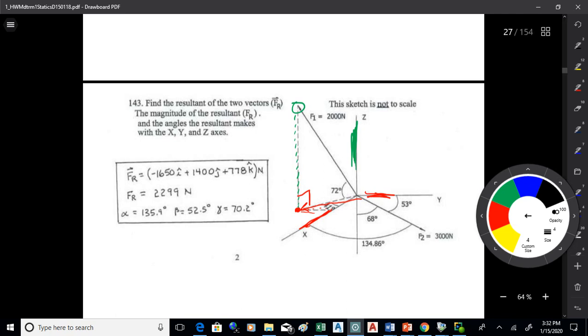So what's happening here is you're given dimension lines that are parallel to the given axes. I give you that dashed line in green right here. That's parallel to the z-axis. That means this line goes straight down in the z direction. Where it lands is on this point over here that I didn't give a name, but it's a point that's directly in this direction, which is parallel to the y-axis from the x-axis, okay?